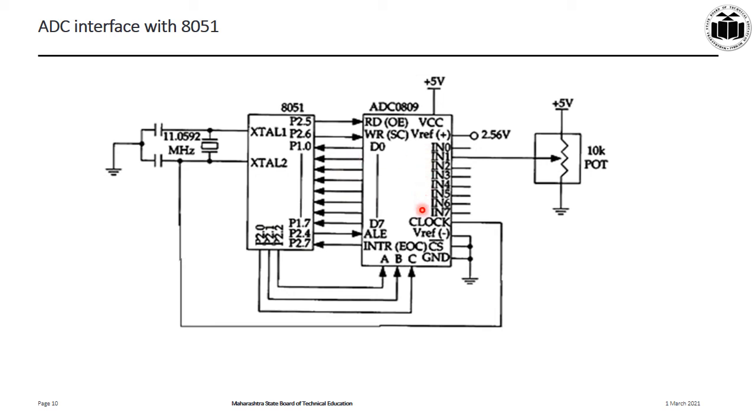Whichever input is selected will be converted to digital, and that data is given to the microcontroller from D0 to D7, and that is on port 1.